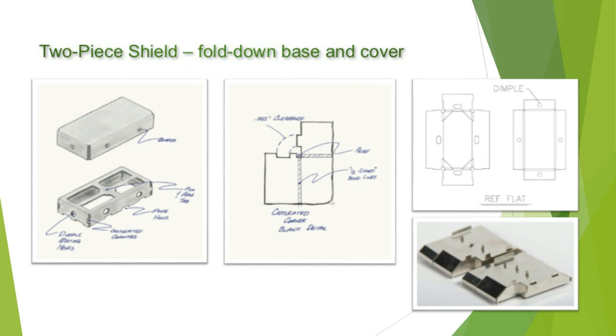Another option for the corners that I didn't discuss yet is sort of a hybrid of the two methods, where you castellate the two corners. You basically have the two pieces of metal extended so they're occupying the same piece of space. You just do it in an interleaving fashion.